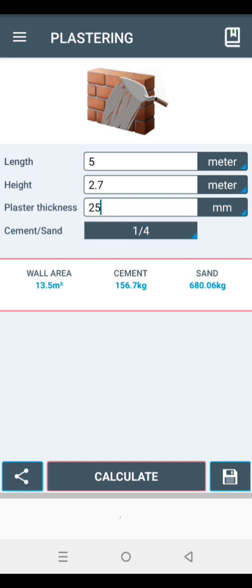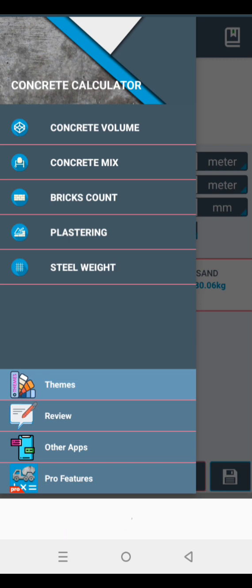In case you want to do the plastering job, you want to use it to calculate the number of, say, probably you're on site, and many of us now, we've known the number of reinforcement in a tonnage. So for assumption now, for 10 mm it is always 133 in a ton. For 12 mm reinforcement, the number in a tonnage is always 93. For 16 mm it is 52. For 20 mm it's 34, and for 25 mm it is 21 numbers.